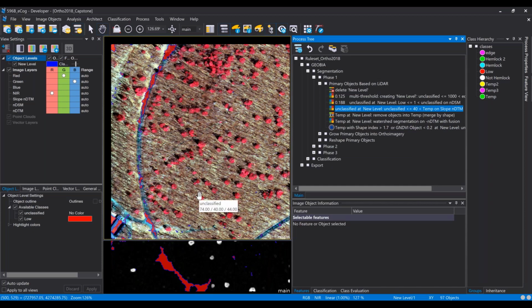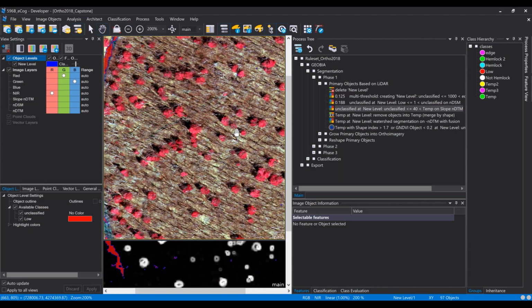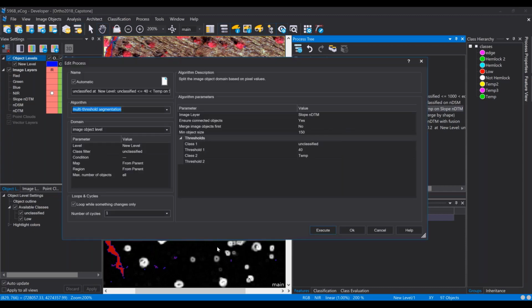And while some objects were representative of them, a lot of times it was very mixed in, and I was capturing a lot of other, non-target area. And I had kind of an object bleed happening. And it seemed like a lot of work to try to fix all those objects and classify them by using the imagery. And so I started out with the Lidar because it was a lot cleaner of a product. And that last return layer with the slope, it was almost like that slope layer was drawing the trees for me.